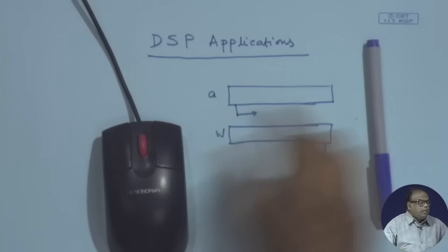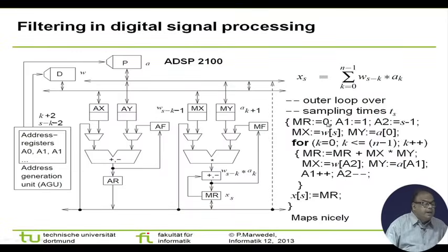So, and I initialize this sum, this is an adder, and what is this? This is an adder also, this is an adder, this is a multiplier, sorry, this is a multiplier and this is an adder. So, all these are hardwired, so that this multiplication and this addition take place in the same cycle. Okay. We are given an instruction, MAC instruction, multiply accumulate. So, we are getting this and the current result is in MR.